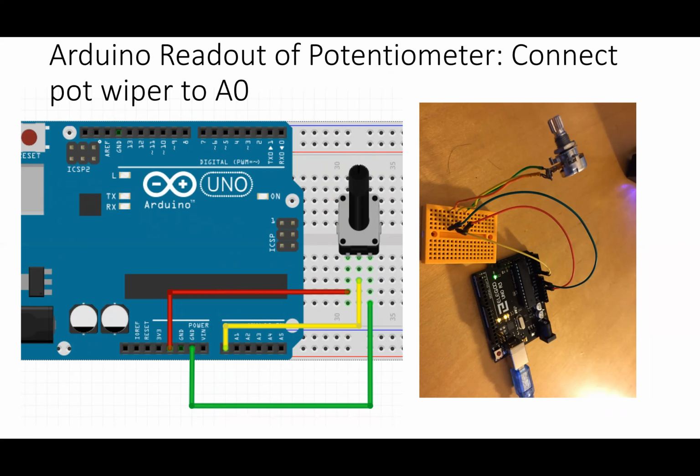Now, let's do what we really want to do in this class, which is to use digital means of reading out voltages. And our digital means are our Arduino microcontroller. So let's wire up a circuit to, instead of connecting this center pin here to the meter, we're going to connect it to this A0 pin. A0 through A5, remember, are the 6 analog inputs.